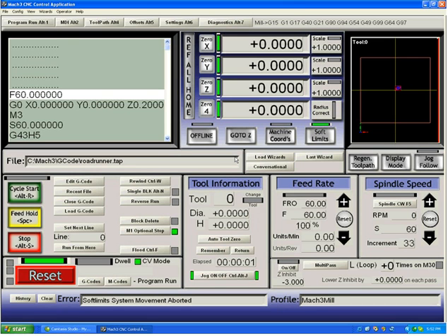There are several things that you can do with offset systems, and there is a third offset system which can be applied to the previous two, and that's the G92 system. One of the reasons I don't recommend using G92 is simply because it can cause confusion to newer users. Users that know what they're doing can use G92.